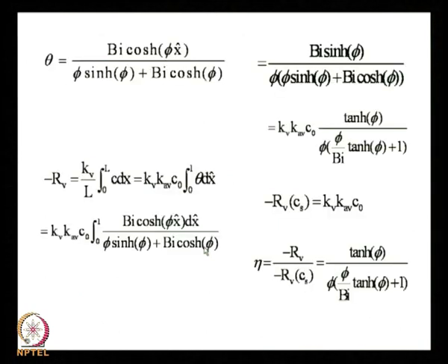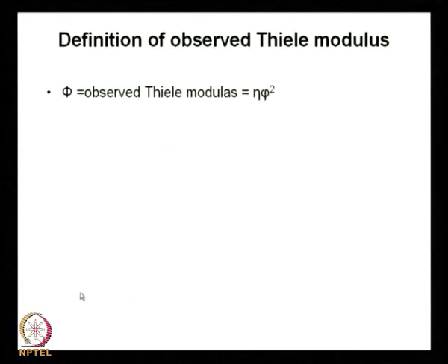Now, what we are going to do in today's lecture is try and obtain a general expression for the effectiveness factor. While we derived the effectiveness factor for the normal slab, I told you that it comes out to be tanh phi over phi, and that this is an expression you can use for different kinds of geometries provided you make certain changes to phi. That is, you define phi in terms of the effective length L. The length L is going to be half the length for a slab, something else for a sphere, something else for a radius, and we will figure out how to do that today. So, that is the first thing we will do today.